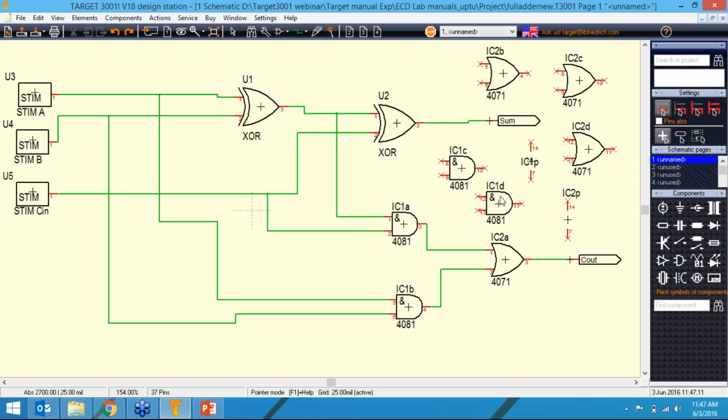So now it is completely imported. As you can see, the 4081 IC has 4 parts. Yeah, 1, 2, 3, 4, all the parts are there. And this is 14 and 7 pins, that is for power. You can provide 5 volt to this power pin.